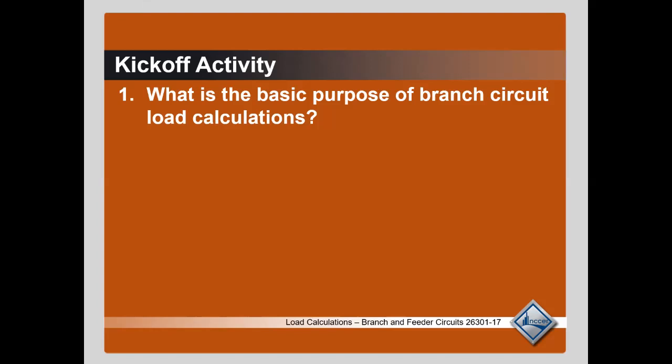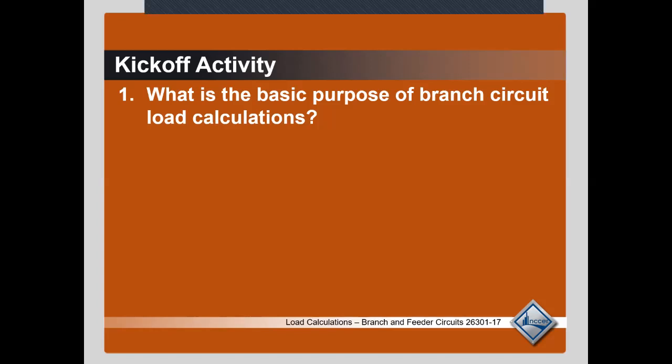Okay, so now what if it was a bakery, like a donut shop? Ovens, fryers, mixers, deep fryers, right? So you'd have to have multiple things. Now a lot of those cookers and stuff are gas, but some of them still have electronic controls on, so they still require power. So they require a different amount of power. So what we have to do is determine what the actual power consumption is, and then build a load calculation from it.